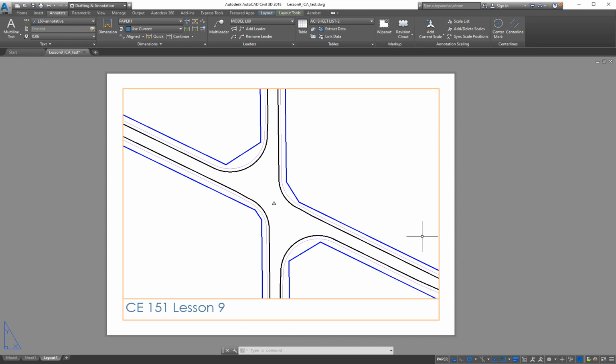All right. So once you get the title block built, you're going to come in here and set up a sheet manager for that. You're going to plot this as well, using monochrome for that. And that'll be it. That'll be today's in class. So hopefully that's a good tutorial, a little background on paper space and model space, and the best ways to look at those, and how to manipulate those, and how to get all those different viewports.